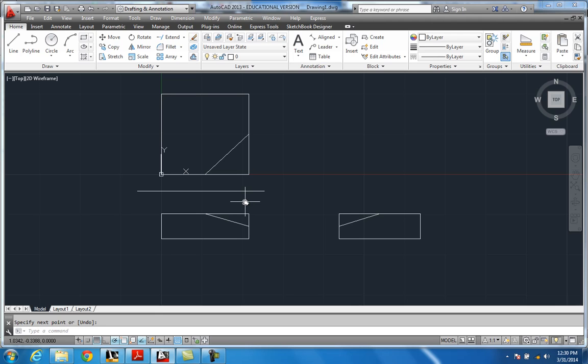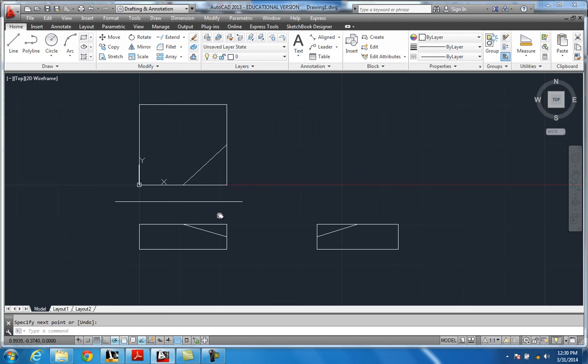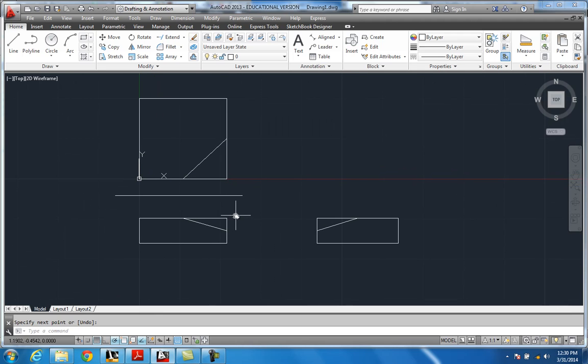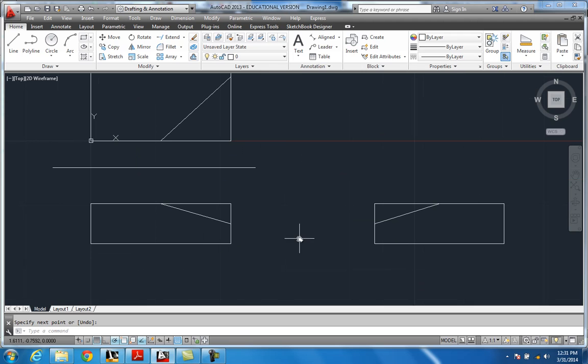There's a few techniques, and again you're going to use some of the concepts you learned in the last two classes. First thing I want to do is find the edge view of this line between this point and this point. When I do that, I just have to fold this up and I would be able to see the whole surface.